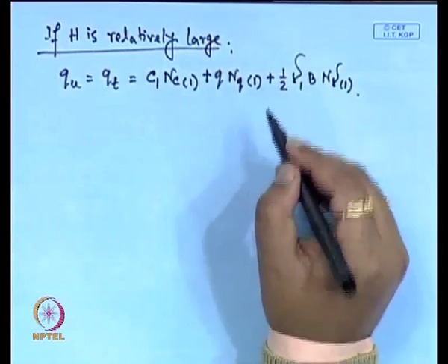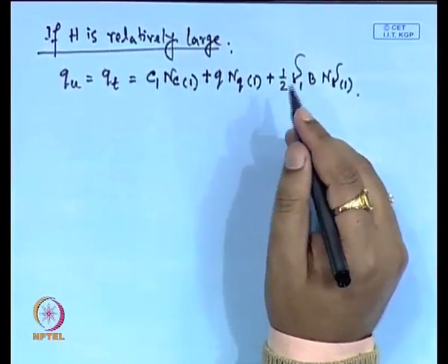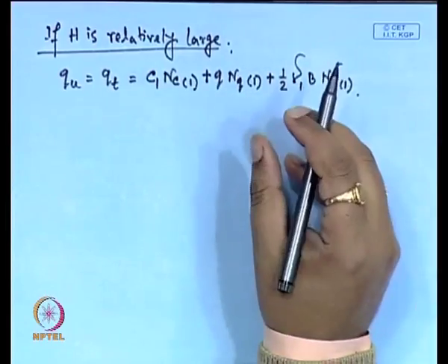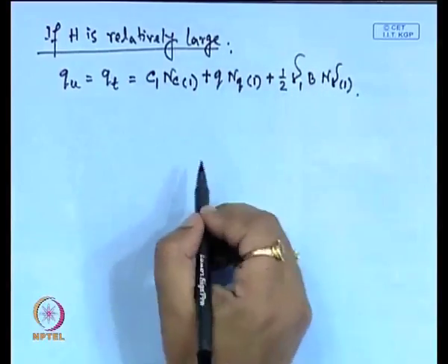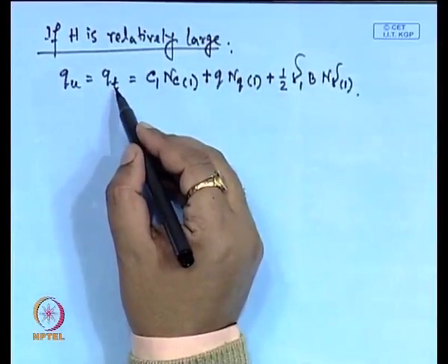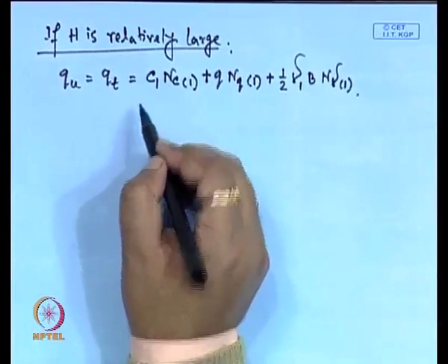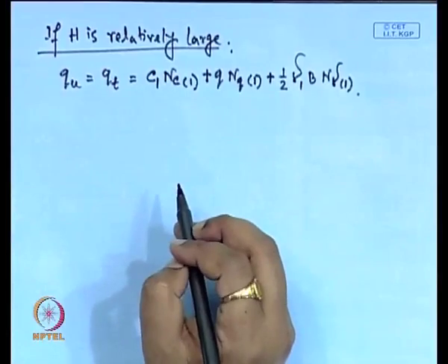Now we can conclude that the top layer is the stronger layer and the second layer is the weaker layer. So, the bearing capacity from the combined contribution of the first layer and the second layer cannot be greater than the bearing capacity of the top layer itself, because the second layer is the weaker layer.